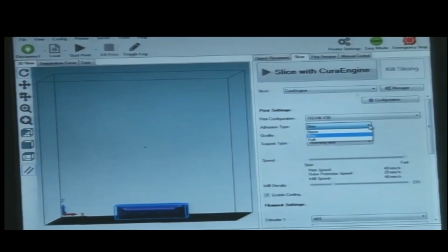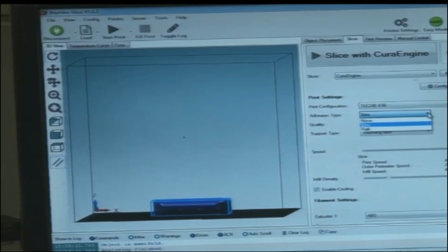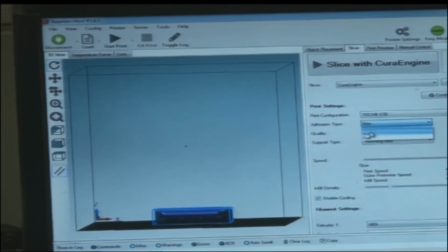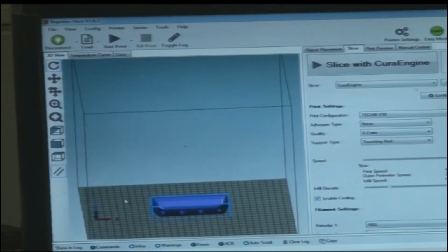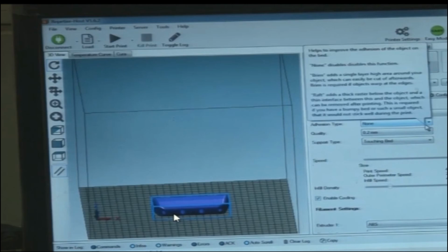It is actually known to the manufacturer that the quality of the product varies with using brim or not. In general, the brim command is preferred to reduce the wastage of the material. The second layer onwards would follow the CAD geometry. In this specific model, the brim and raft are only the first layer, as I mentioned before. But in certain machines, raft can be more than one layer. So we have just kept it as none. That is, we are not getting any brim or raft here.